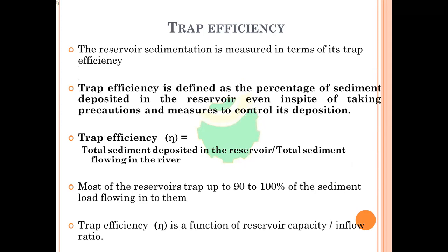The life of reservoir calculation mainly depends on the trap efficiency. What is the trap efficiency? Trap efficiency is defined as the percentage of sediment deposited in the reservoir, even in spite of taking precautions and measures to control its deposition.